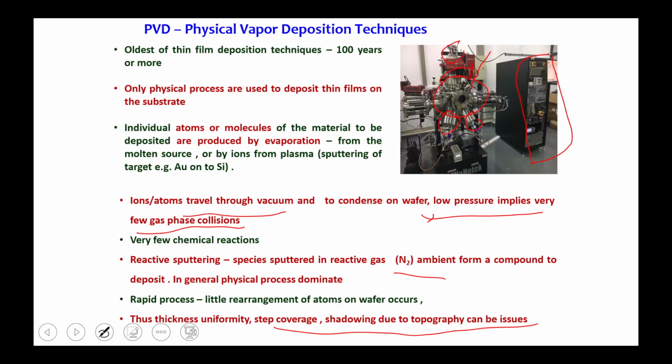What will happen is that some material will also cover the step, and you cannot get a proper step to see where the substrate is and what the thickness of the metal is. So using PVD, the step will also be coated with metal? Yes, sometimes. So it will be difficult to make a proper step.